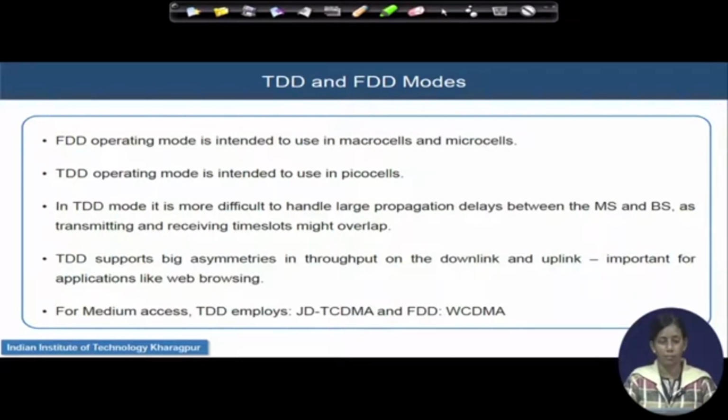So, you have maximum flexibility in the WCDMA system to go ahead with multiple classes of operation based on the bit error rate requirement as well as the time delay associated with it. And that is why we saw the 4 different classes of operation based on the kind of communication you are trying to do. For example, voice will be related only to the conversational class, while streaming mode will always be associated with audio video streaming, and hence their bit error rate requirements and delays will be completely different. The 2 other remaining modes, for web browsing, SMS transmission and email sending, are different from the previous 2 modes.